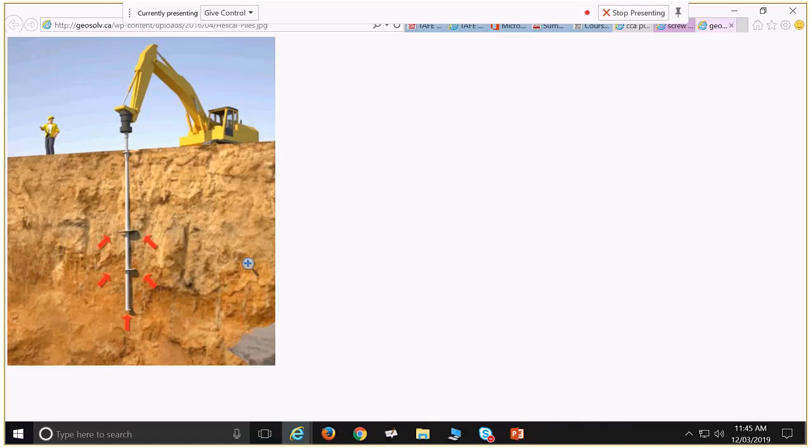Another really cool thing is that you can put screw piles in like that. So you put them in with an excavator. So you've got an auger driver section on top of your excavator, and also I'll go into that later. But you can put screw piles down, put a building there, then decide, okay, let's take that building away, let's dismantle it, let's take everything away, and unscrew the piles and go without, basically not leaving a trace on the site.